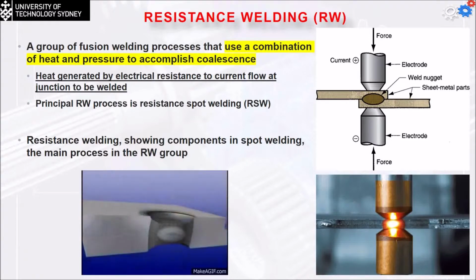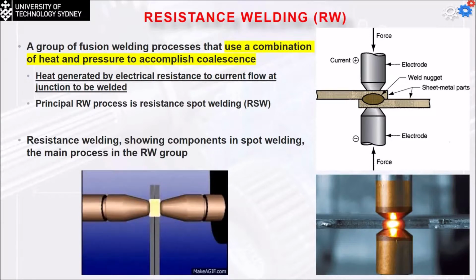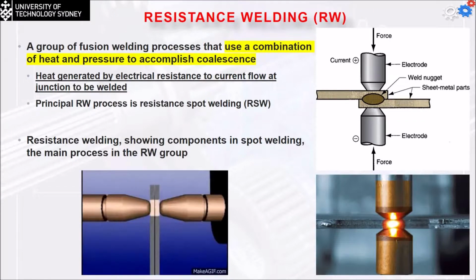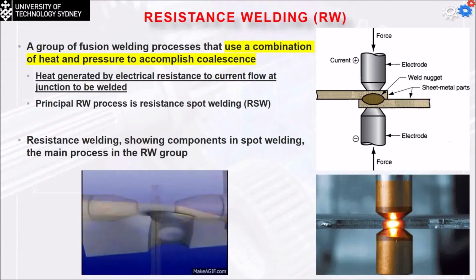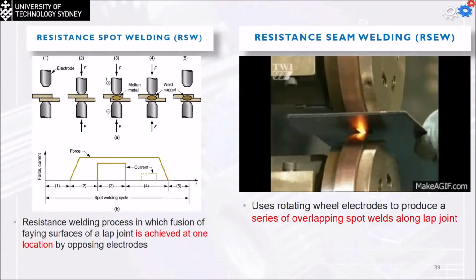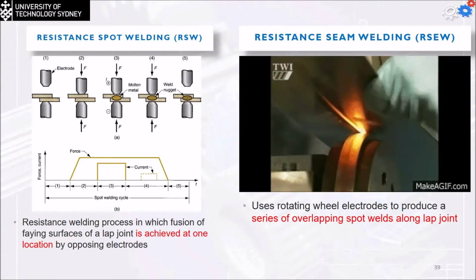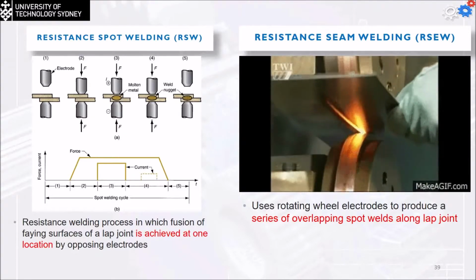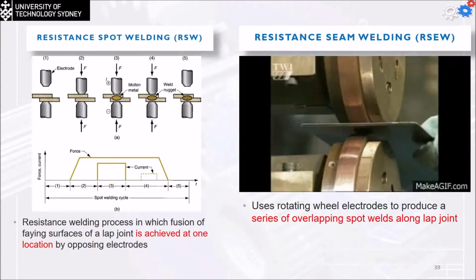Once again, we can make it resistance spot welding, just a spot between the two plates, or I can make it what we call line welding or seam welding. These are the two poles, the positive and negative. I pressurize the two plates together, and we have a seam, or line, instead of the spot. Also, I can have it as the resistance projection welding type.